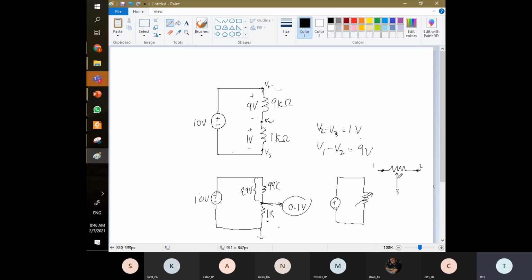This one can be adjusted to the far right and the far left, to adjust the ratio. If it's adjusted here, that means 0, right? If it's adjusted here, it's the full resistance. So from here we can use it as a voltage divider. We can divide the voltage into a 1:9 ratio, or a 1:99 ratio, right? All this is called the voltage divider.